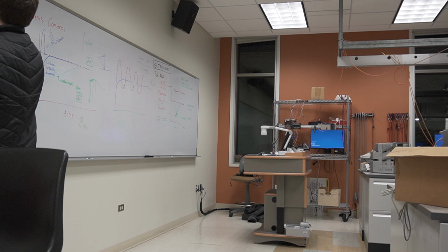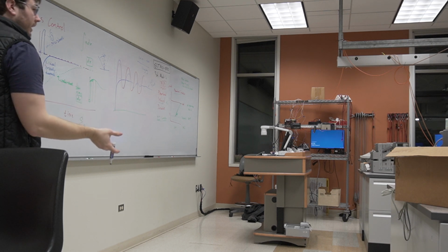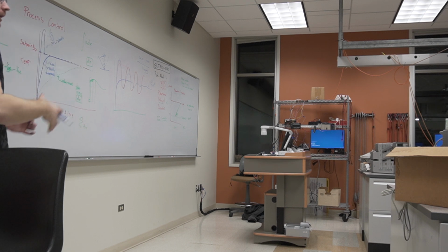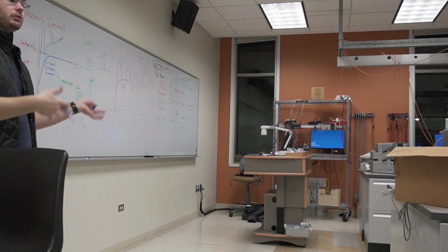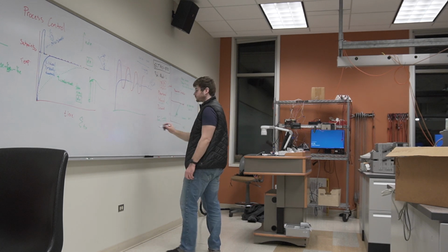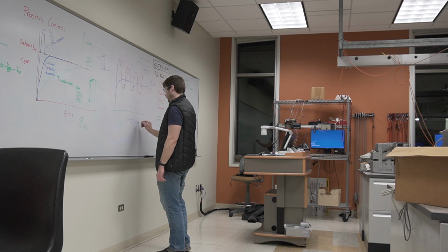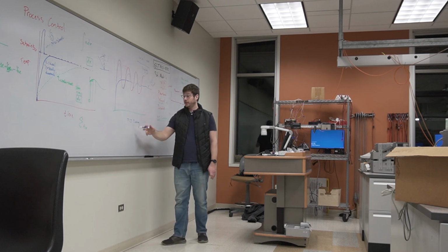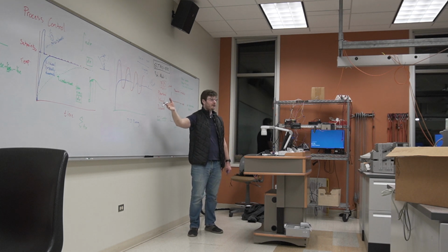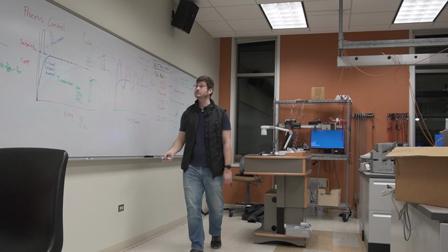But more often than not, you just have to pick a P, call it like 0.5, and then tune that, and then pick an I and see how that works, and then raise I or raise P or lower P. So tuning a system, that's why they really call it PID tuning, is you sitting down with the thing that you're controlling and tweaking these parameters until it starts to work well. It sounds like not right, but that is very often what happens.